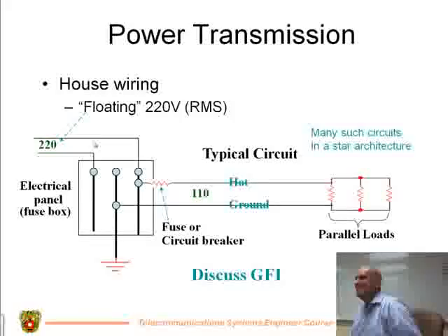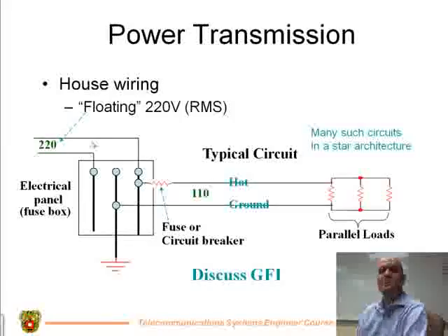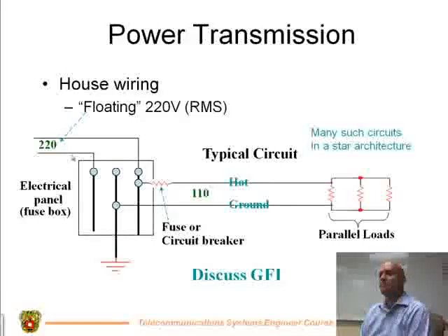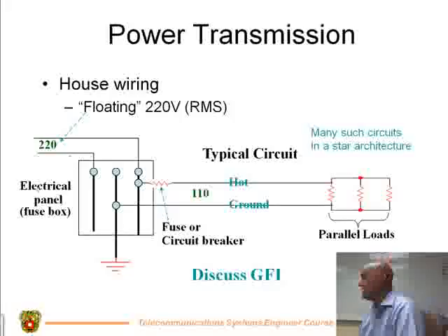Oh, crap. Well, the funny thing in housing, too, is none of the outlets in the upstairs master bathroom are on it, the control circuit's further somewhere else. It's not even in there. Right. If we got one in the garage that controls some of those outside outlets that you might look at. Yeah. It's odd places. So the moral of the story is if you've mysteriously got your power out in part of your house and the breaker's not popped, start looking around for GFIs in just random places. Make sure they're all still set.